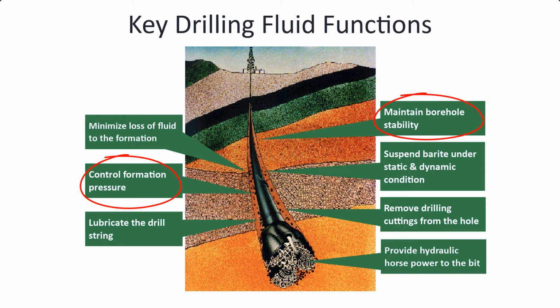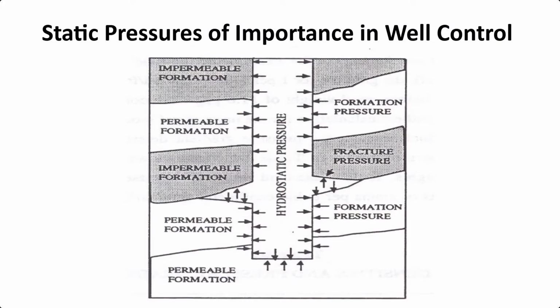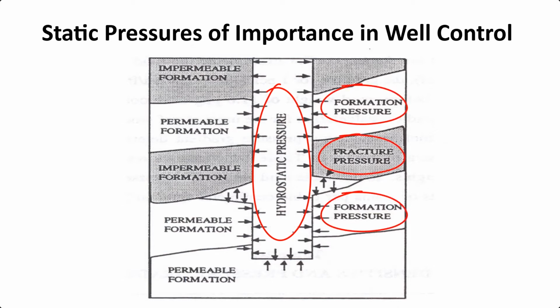The specific gravity of the drilling fluid is increased by adding solids to the drilling fluid. The rheology of drilling fluid must be such that the solids will be held in suspension, for example, suspend barite under static and dynamic conditions. This figure shows the static pressures of importance in well control. These are mud hydrostatic pressure, formation pressure, and fracture pressure.